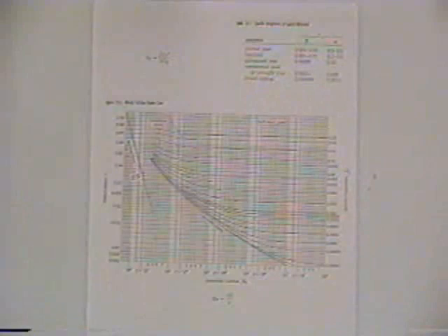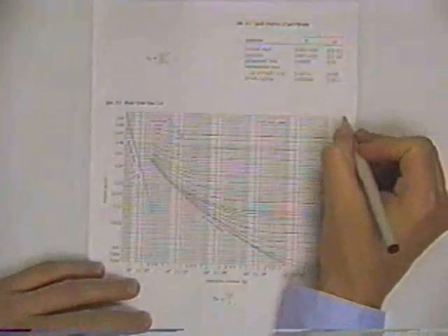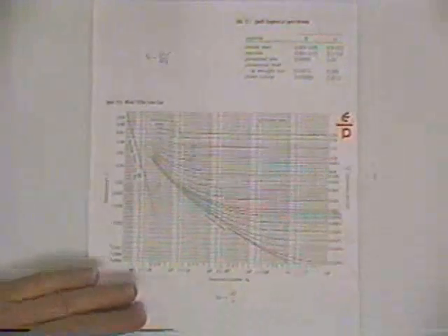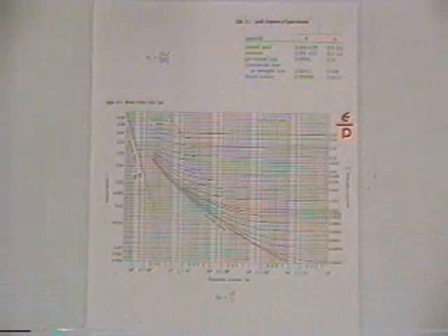Now if you've got a rough pipe, but it's a large diameter pipe, it's going to have a different effect on the flow than the same pipe material, with the same amount of roughness represented by epsilon, but a smaller diameter. So what's really going to count is the relative roughness, which is the absolute roughness on the inside of the pipe divided by the diameter. On this scale of the Moody diagram, we've got the absolute roughness divided by the diameter of the pipe. Friction factor is going to depend upon the characteristic of the pipe.